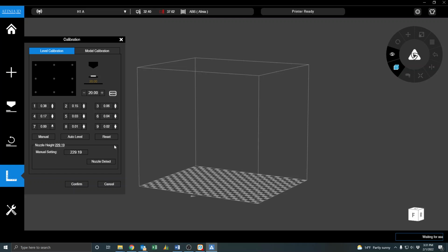The levelness of a platform is crucial for good prints. It's critical to not have failures of the extruder. You want a level platform, and when I say level, it's not level to the ground, it's level to the XY path of the nozzle itself.